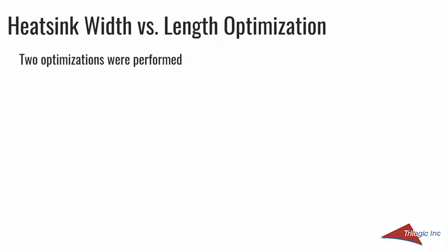So I used response surface optimization, which takes the results of the design of experiments, and it does two things. First, mathematically, it tries to estimate where the optimum is. So what's the optimum width and length and base thickness. But it also gives you the plots and data to study the sensitivity of these design inputs, which I think are just as valuable really as the actual optimum.